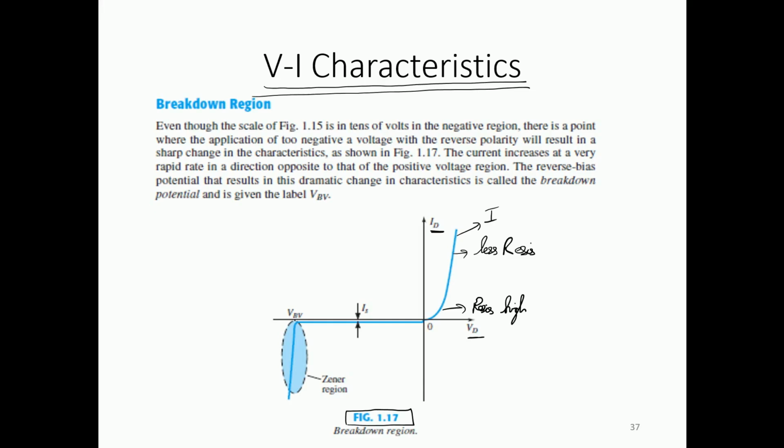Keep in mind, we don't want to increase the voltage much, because in the forward bias direction there is a limit towards the maximum current. If we increase the voltage beyond the values provided in the data sheet, the diode can also get damaged in the forward direction, so we keep it at a nominal value of voltage.